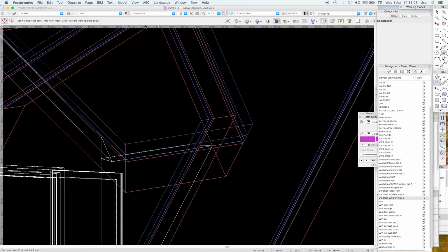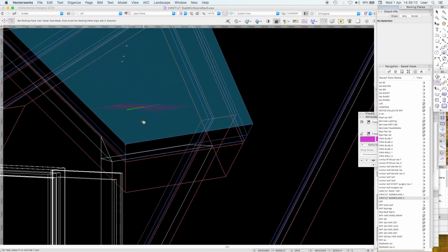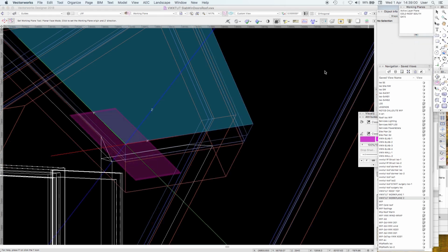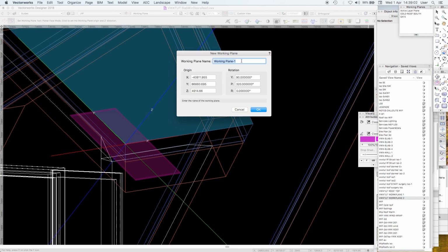This time we'll use the set face. It's picked it immediately. There'll be times where you'll find it's not picking the right plane, because if the plane has no orthogonal corner, that corner we're looking at is actually 90 degrees. That's fine. So my x and y axes are 90 degrees. If you've got an object which doesn't have a 90-degree right angle in it, then I would always recommend set by 3 points. Straight away save your new working plane. So this is going to be cold dormer.